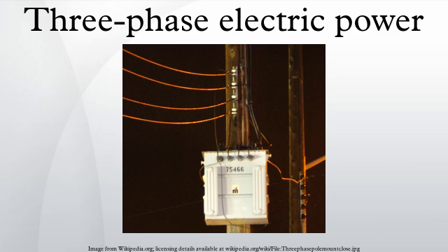There are two basic three-phase configurations, delta and Y. As shown on the left, a delta configuration requires only 3 wires for transmission, but a Y configuration may utilize a fourth wire. The fourth wire, if present, is provided as a neutral and is normally grounded. The 3-wire and 4-wire designations do not count the ground wire used above many transmission lines, which is solely for fault protection and does not carry current under non-fault conditions.